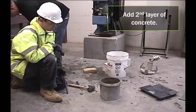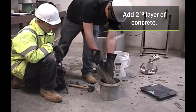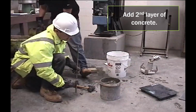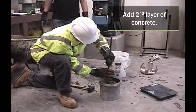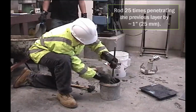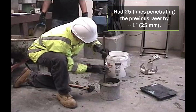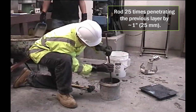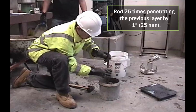We can now add the second layer of concrete, again moving the scoop around the perimeter of the bowl to ensure even distribution and minimize segregation. The second layer should fill the bowl to approximately 2/3 its volume. We now want to rod the second layer 25 times. The second layer is rodded throughout its depth, penetrating the previous layer by approximately 1 inch, or 25 millimeters.